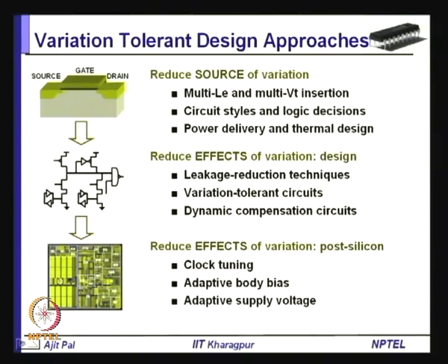That means, instead of discarding them, you will divide them based on the frequency of operation, you will put them in different categories or different slots of frequencies, and this is known as frequency binning or clock tuning. That means different dies will operate at different frequencies; after the fabrication you will do measurements and then distribute these dies to different clocks or different frequencies.